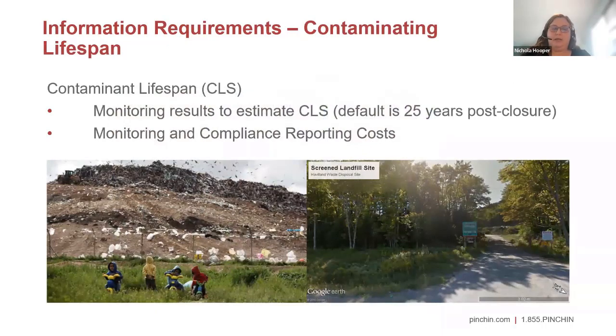Contaminating lifespan. Another thing that's important is the contaminated lifespan of the landfill. The landfill is a significant source of potential contamination. When it rains, it will create leachate, which will potentially enter into the groundwater. So you have to have a leachate management plan for the site. So it's something that you need to consider.